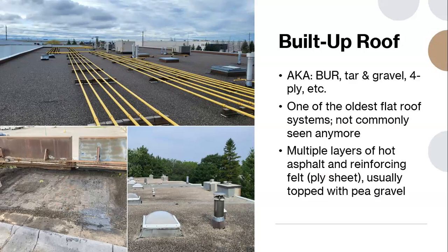This membrane system also, typically when we're running into it, is on an older building and is an older system that's reaching the end of its life. This system is typically prone to splits and cracks during the winter months when extreme temperature fluctuations are causing expansion and contraction in the membrane.